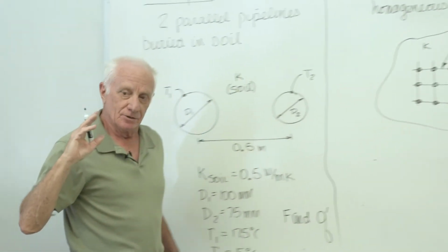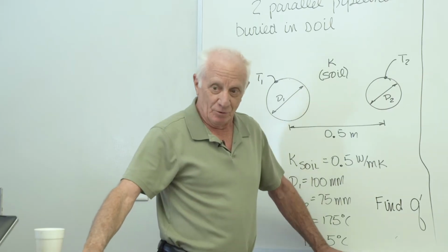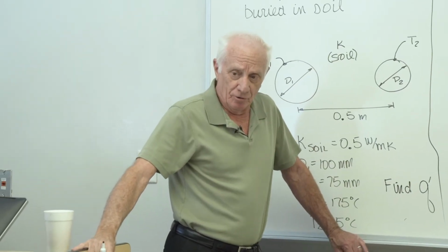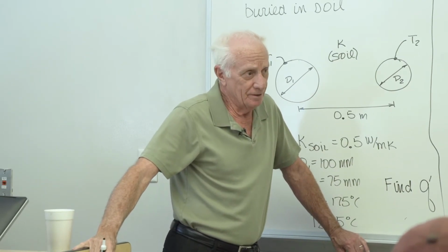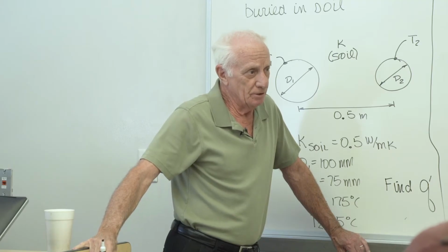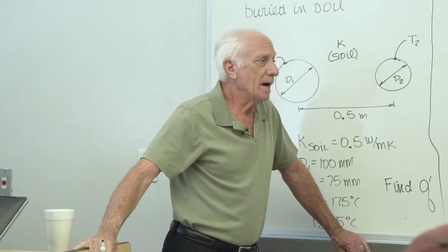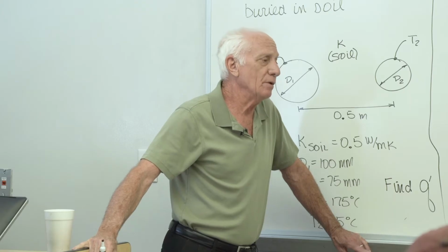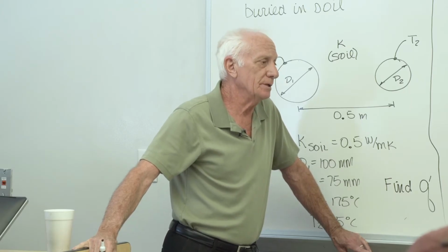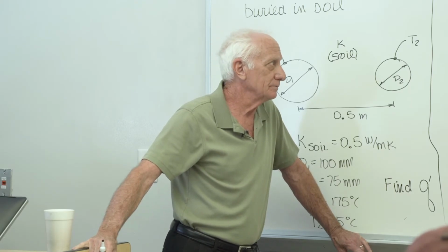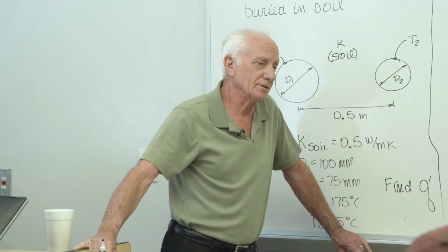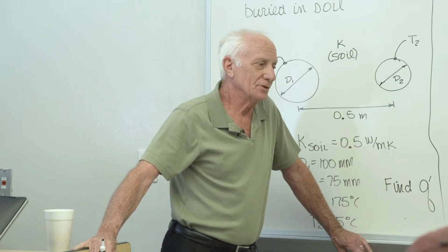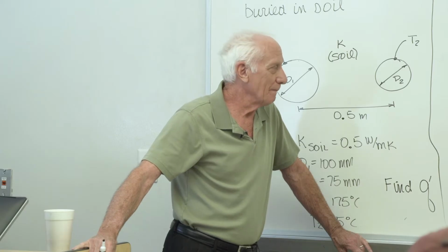So we replace the homogeneous material with the grid, and at the nodal points, that's the temperatures in the body, and these different temperatures are connected to each other by heat conducting rods. The only way heat's conducted then is through these heat conducting rods. So it's an approximation, obviously. We'll see later on how good it is.